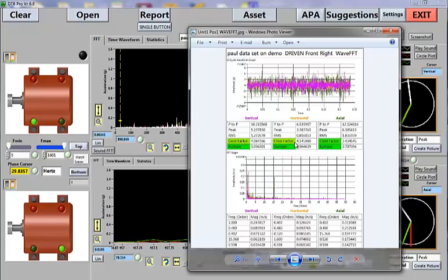You can see the crest factor colors are starting to light up. They're a little bit less green. As the values get more and more indicative of faults, they will go more and more towards red. So it'll go through green to yellow to orange to red. And right here you can see that these crest factors on the vertical and horizontal of the driven on this outboard side are starting to show some sort of high vibration potential issue.